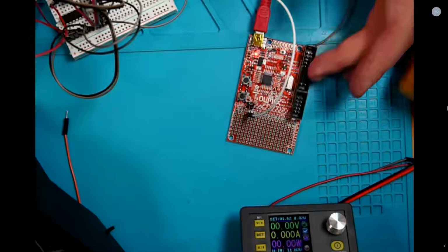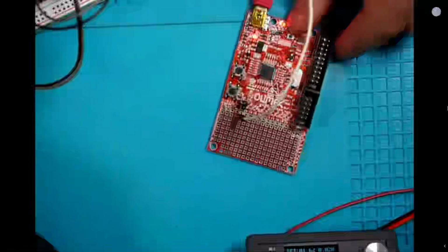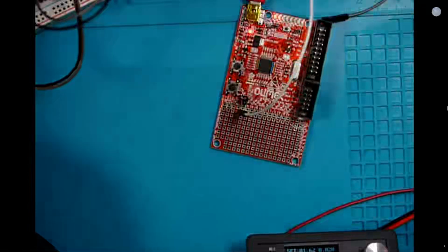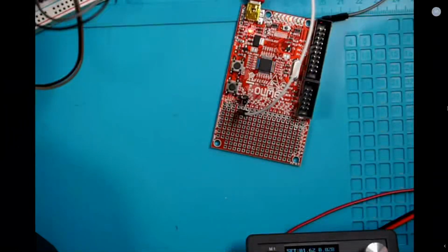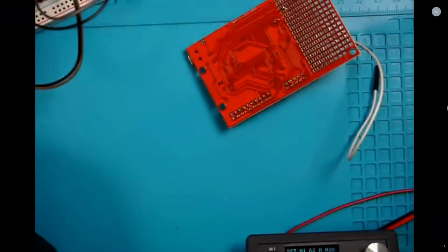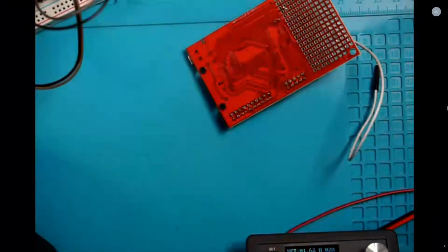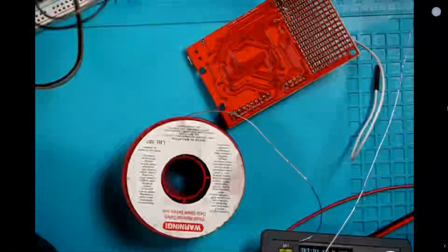Fortunately, we have this JTAG connector right here. This JTAG connector has almost all the signals that are ground. A bunch of them are unused. So we can actually use that and connect the signal there. So I'm going to unplug it, obviously, because you can short something while soldering. So I'm going to leave it there. And so I'm going to solder this connection. So 4 and 2, I'm just checking one more time. And it should be this one. Looks good. So obviously, if you have the choice, always use leaded solder for this kind of stuff.